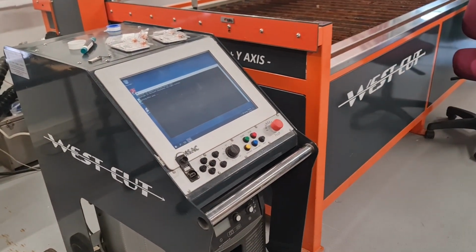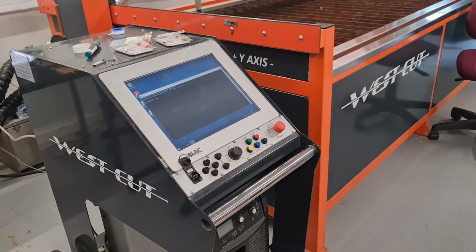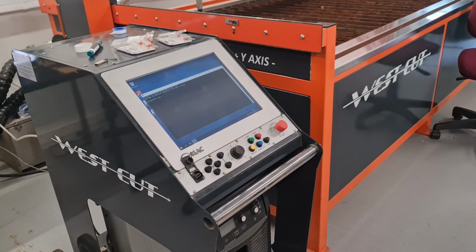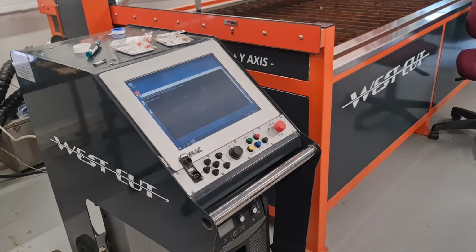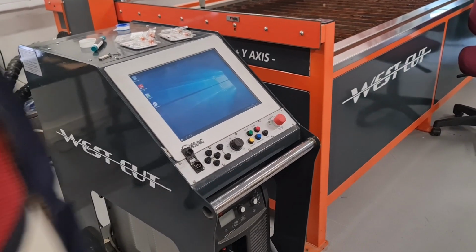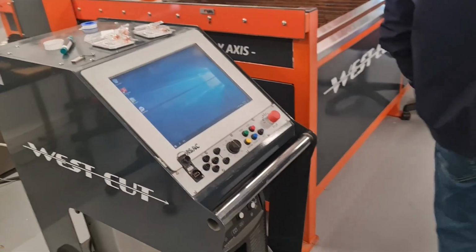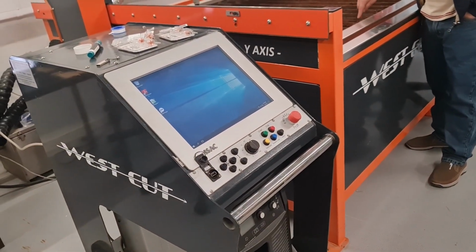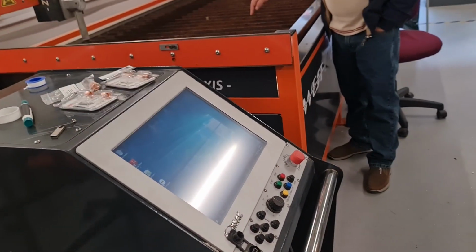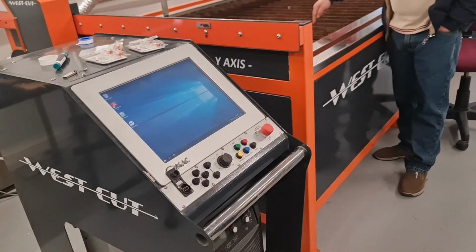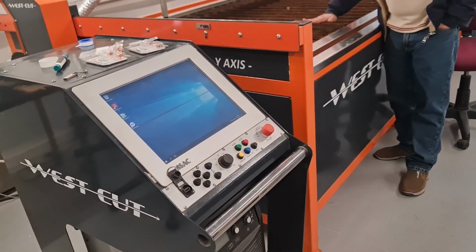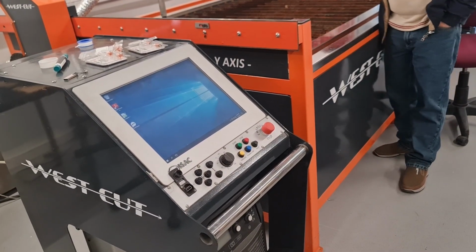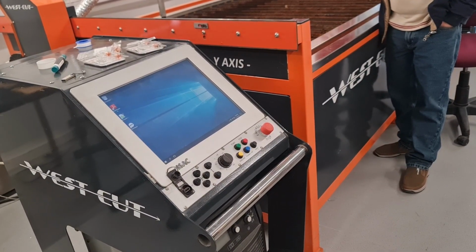What's the thinnest metal you can cut on here? The thinnest, yeah, if you go fine cut, I think 1 mil is okay. The problem is mainly because you have space here, or you can add more here. When it goes and finds the top of the material, this will bend because the shape will be thin and it doesn't find the correct height.